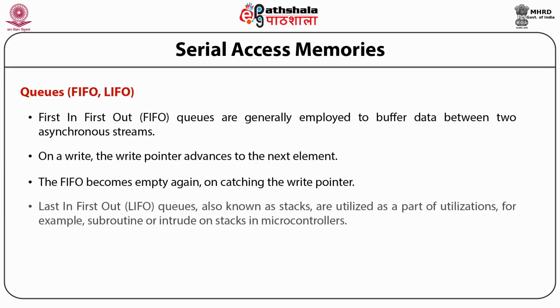Next is last in, first out, LIFO queues, which are known as stacks. They are utilized in applications, for example, subroutine or interrupt stacks in microcontrollers. LIFO utilizes a single pointer for both read and write.